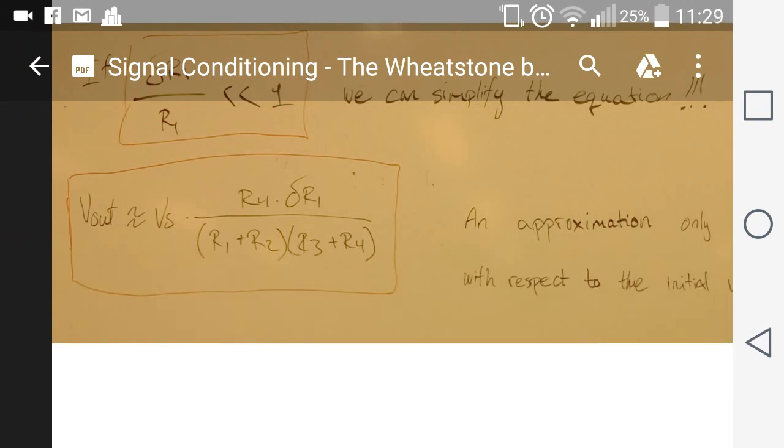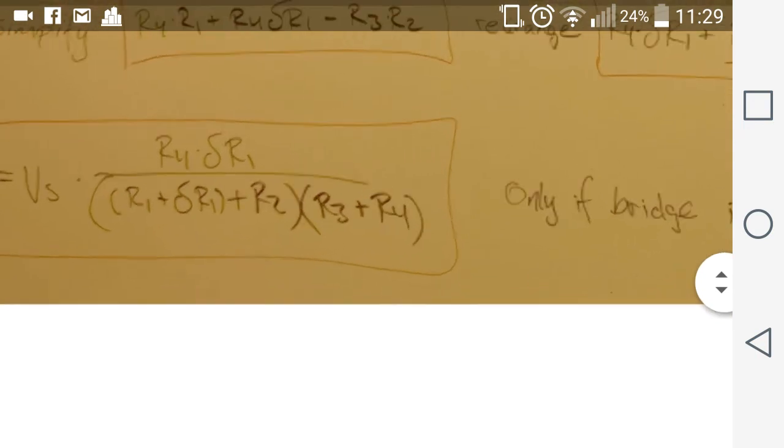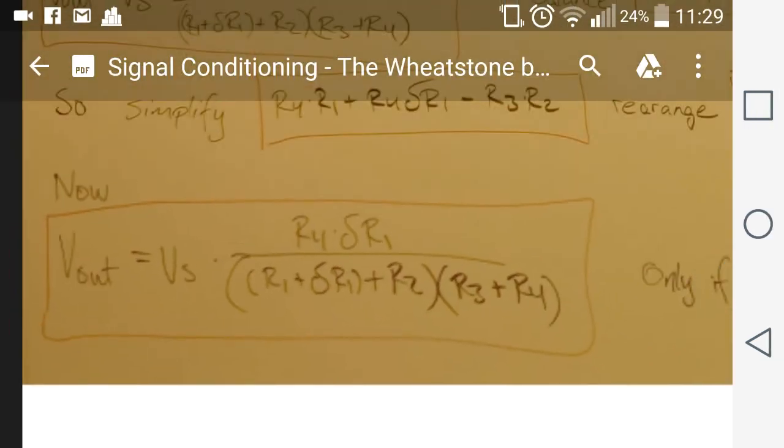So we have talked about how the voltage divider works, so that we could use it when analyzing the Wheatstone bridge and find the output voltage when the bridge is not in balance. We were, for example, using a sensor instead of one of the resistors. If you want to replace more than one resistor in the bridge with sensors, then just remember to take account of that in your equation as well.